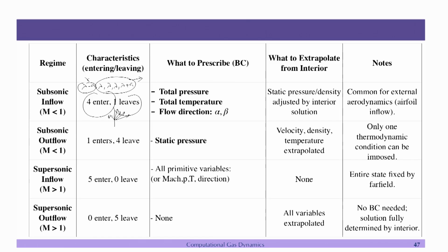So, that is basically you give the pressure which is coming from the CFD solution on the interior point, and at the inlet either you can specify basically rho, u, v and w, and p is coming from the interior. Or a better way to do it is basically specify total pressure, total temperature and flow direction. So, with this and the p from inside you can actually calculate u, v, w and everything.